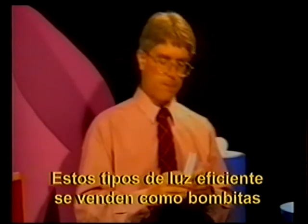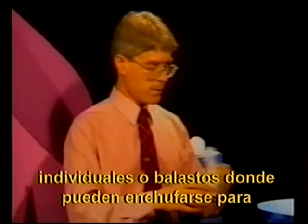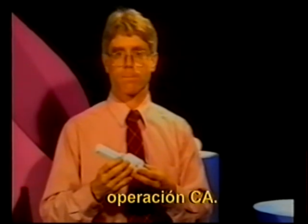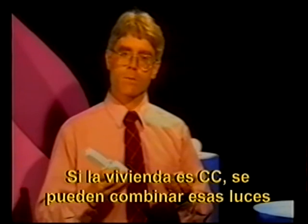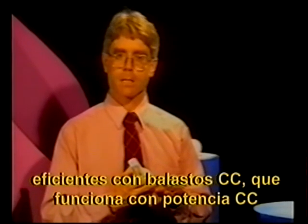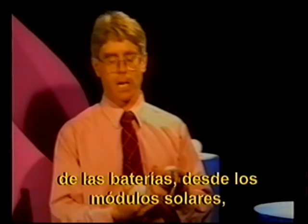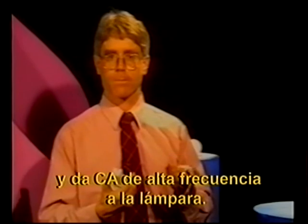These types of efficient lights are available both as individual bulbs or with ballasts that they can plug into for AC operation. If we have a DC home, you can combine those efficient lights with a DC type of ballast that operates from our DC power, from our batteries and solar modules, and outputs high-frequency alternating current into the lamp.